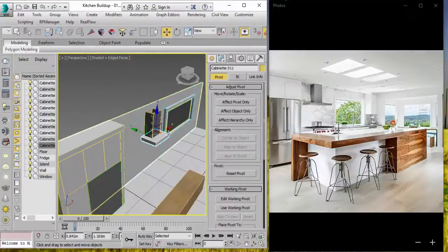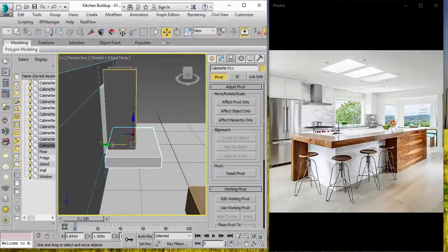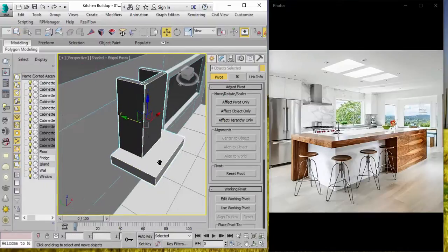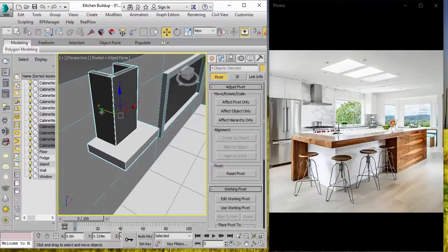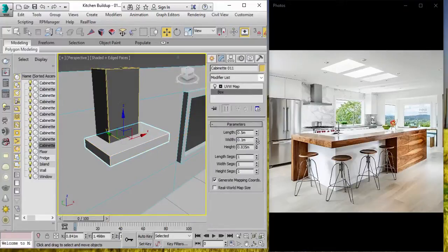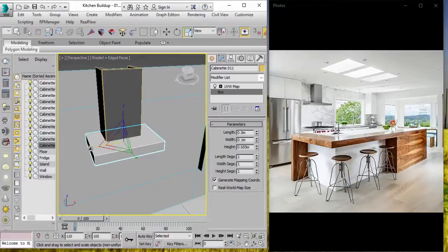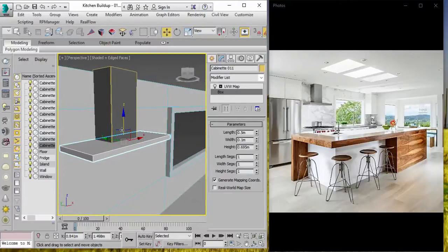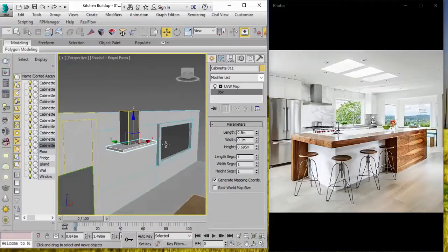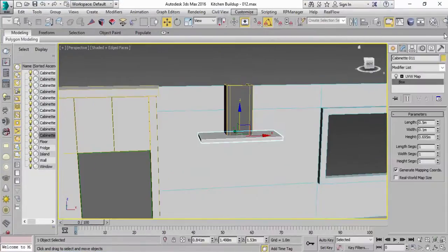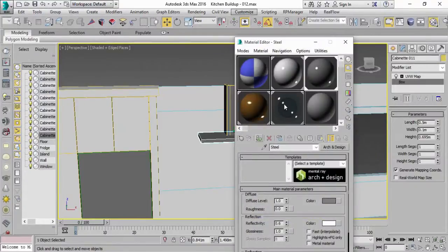There we go. And then you decide, of course, on the dimensions. Well, first things first, we need to select these objects, and they all need to go against the wall, like that. Okay. Then we select the box, and then adjust its properties. It needs to be much longer than what it was before, or rather, let's just undo this. Instead, we're going to scale it. So the extractor needs to be something like that, and of course must be thinner. There we go, and make sure you just align it. Okay, all right. And of course it will also need to be a steel structure. So for the material, we're going to assign, of course, the steel.